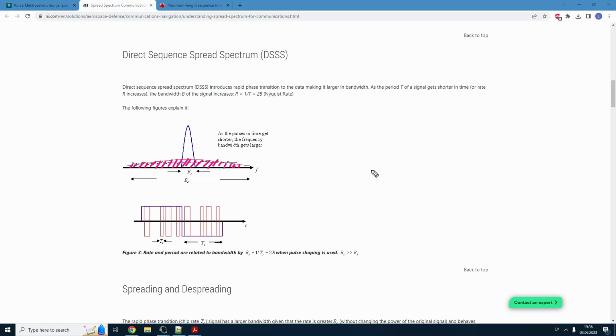So you may think that this will lead to problems with receiving this signal. However, I will tell you it's actually possible to design a system in such a way that the spectrum of the useful signal would be so wide that it will be beneath the noise level, meaning that there will be no way to tell if you are transmitting something or not, unless you know how to receive such a signal, and accordingly this is considered a secret transmission, in a sense.